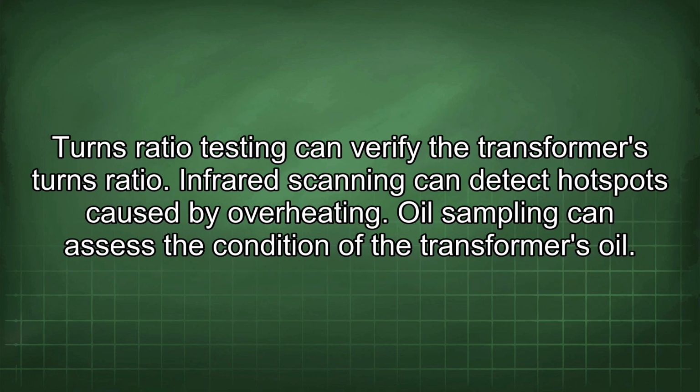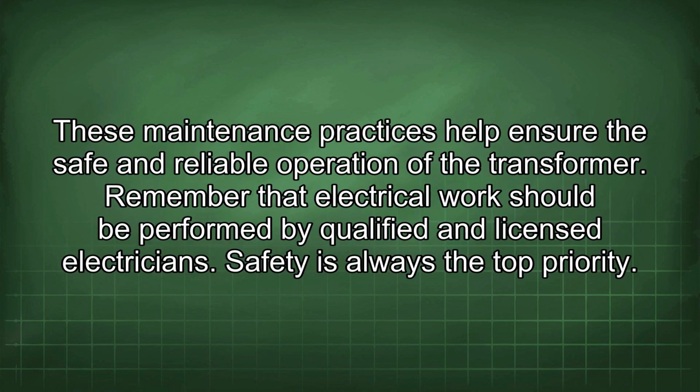Turns ratio testing can verify the transformer's turns ratio. Infrared scanning can detect hotspots caused by overheating. Oil sampling can assess the condition of the transformer's oil. These maintenance practices help ensure the safe and reliable operation of the transformer.